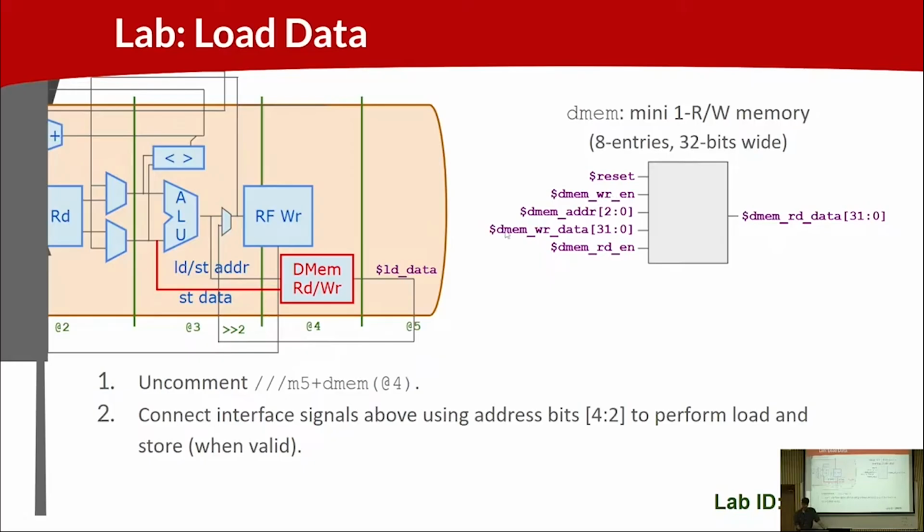And the write enable and the write data, and then on the read side we're using the same address input and a read enable. And for reads or loads, same thing, we have data coming back. So we have read data, which becomes our load data. So hooking this up and giving the signals names that make sense in the context of a CPU, right?